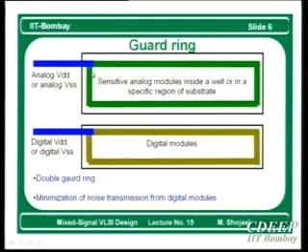What does it mean? It means that the entire substrate which is beneath this circuit is connected to VSS or VDD, so it is almost biased properly. Therefore, if there is any switching noise coming from the digital side, it is stopped here because it is already biased. This is like a barrier for the switching noise coming from here.